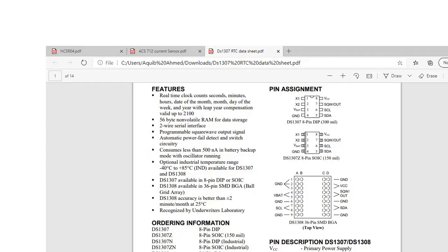RTC, real-time clock. An RTC maintains its clock by counting the cycles of an oscillator. It has an external 32.768 kHz crystal oscillator circuit or an embedded quartz crystal. It can detect transitions and count the periodicity of an input that may be connected.